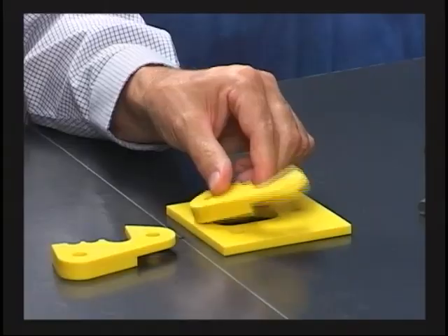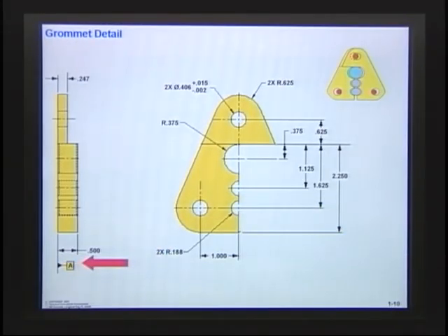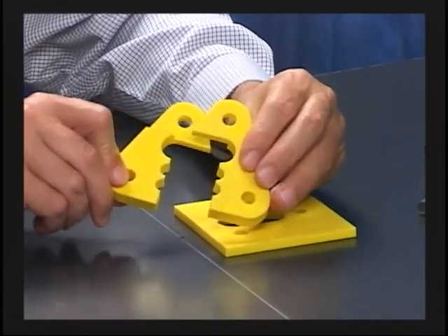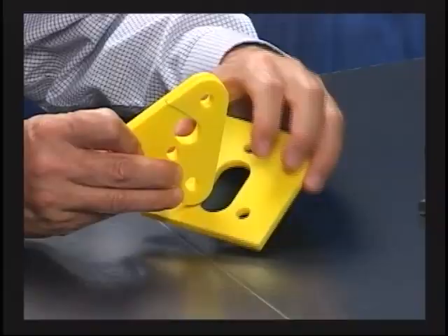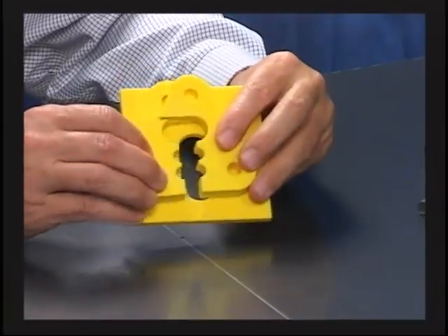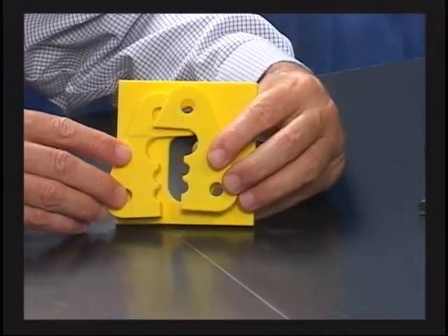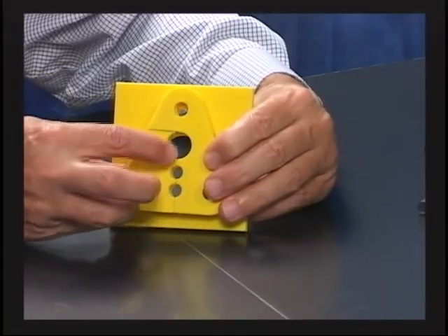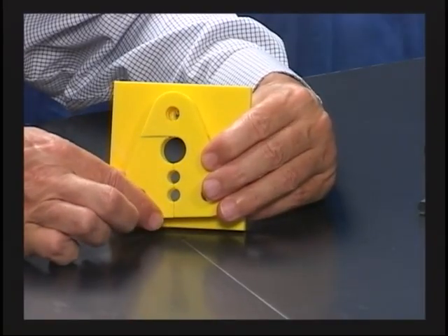All right, now let's take a look back at the graphic. Number 2, what did I select as my secondary datum? I call that surface datum B, and I call that surface datum C. Now, why did I do that? Well, this is what I thought. When the parts were coming together, you see how they're coming together? I take these two parts and put them together. First of all, they come together on the bulkhead, so that was my primary face. Then you see how they come together here, and I push them? You see how they locate one to the other? I push it tight up against that face, you see it comes right up against that face. That I call my secondary datum.